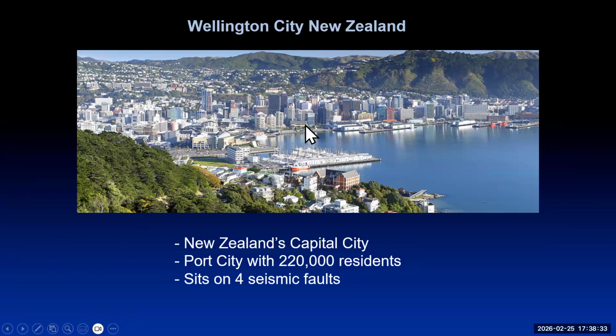1 hertz. So what happened, based on the orientation of the buildings and their natural frequency, some of them really, really rocked. And when I say they rocked, they displaced a lot because that ground frequency, that ground wave aligned with the structural resonance, not just a fundamental, but the second order mode. So it affected buildings that were like 6 to 10 stories and buildings that were like 20 to 30 stories because that was the second order mode at that 1 hertz frequency. So it's really interesting. They actually had to demolish 30 buildings when an earthquake hit 100 miles away.